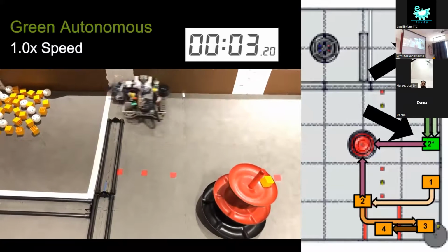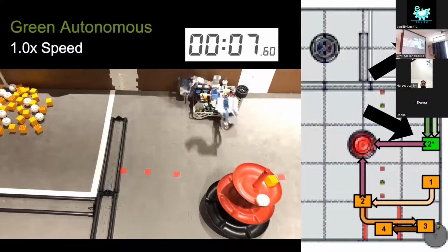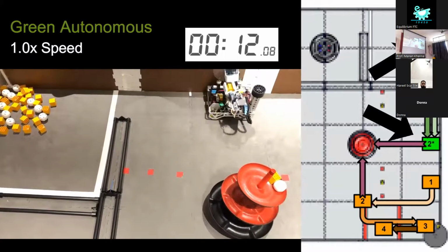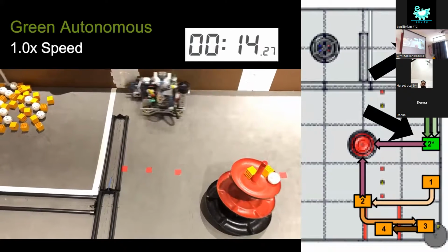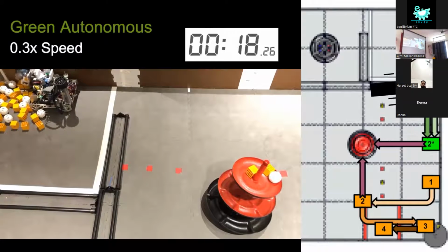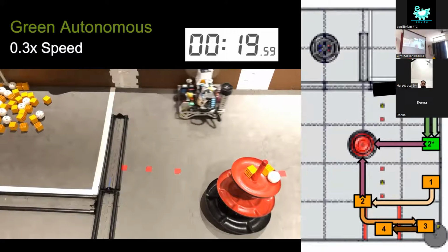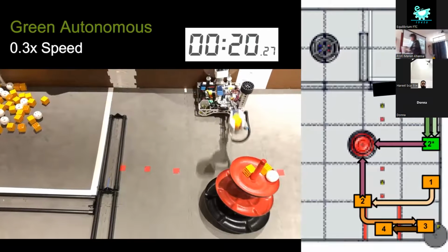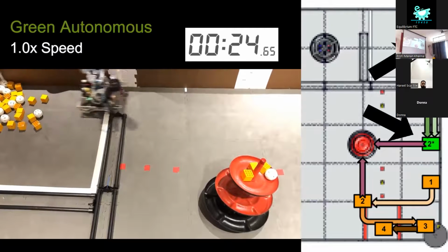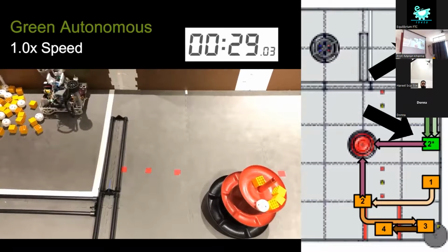Through the use of Roadrunner displacement markers, the robot is able to perform other tasks while moving on its trajectories, such as extending the outtake slides. The robot is able to use the Roadrunner library to automatically correct for trajectory errors in additional cycling. The robot also utilizes a color sensor in the intake to see if it has picked up any freight during cycling.